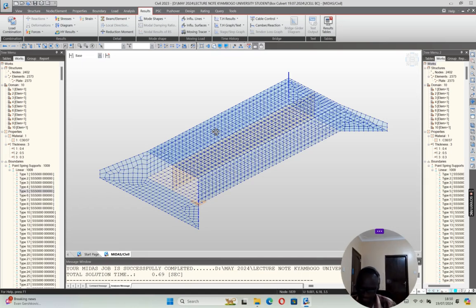So that gives me 44 kilonewton per square meter at the base. Remember that since it is already filled by 0.5, this is at 4 meters. So the lateral pressure at 0.5 will give me 0.5 by 0.5 by 22, and I would get 5.5 as my first lateral pressure at the top of the culvert.